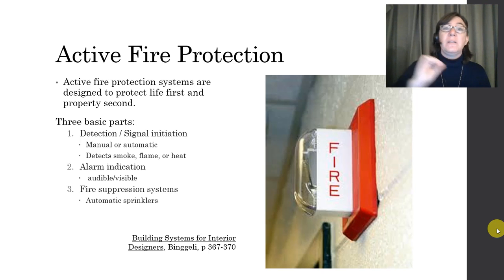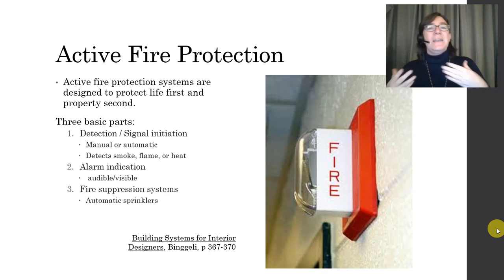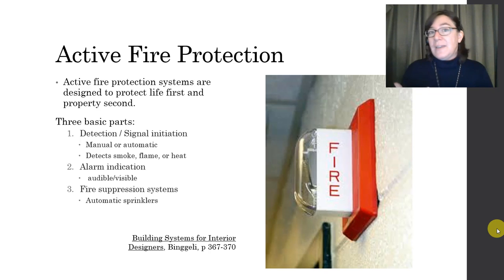The first one is fire detection, also called signal initiation. And this is your smoke detector system. It can also have a manual initiation, as in like a fire alarm pull station. So your detectors will, in general, detect smoke, flame, or heat, right? And they will initiate a signal to the alarm system.